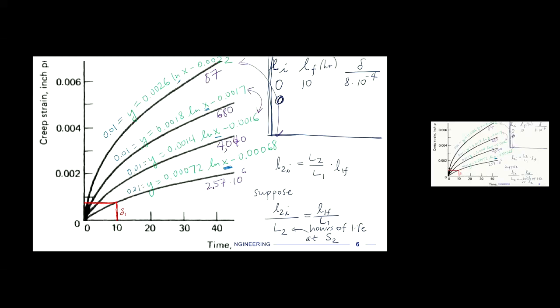And so we start the second phase also at 0. Then we go out 20, so we end at 20. I'm going to draw that on the plot now. If I take 20, and now we're at the second stress level, we go straight up to 20, draw it back all the way to 0. So if I come over, that's the strain that I'm adding for the second stage. In that case, I get like 0.0022, something like that. So we're going to go 2.2 times 10 to the minus 3.